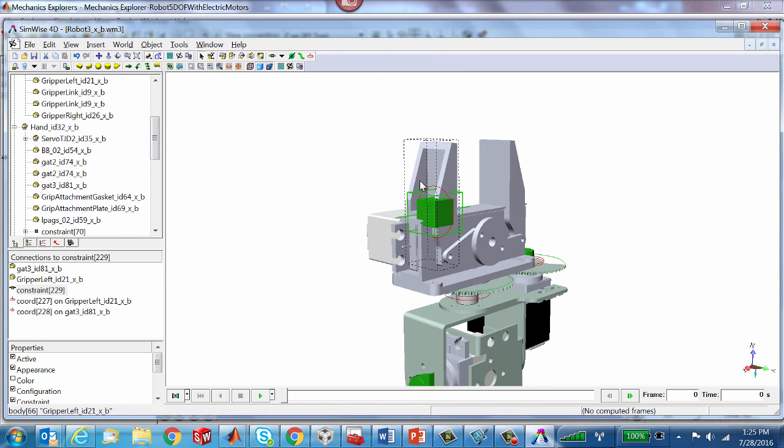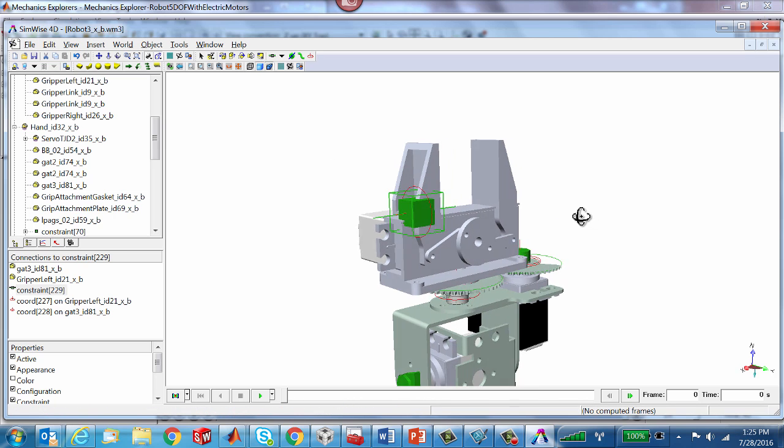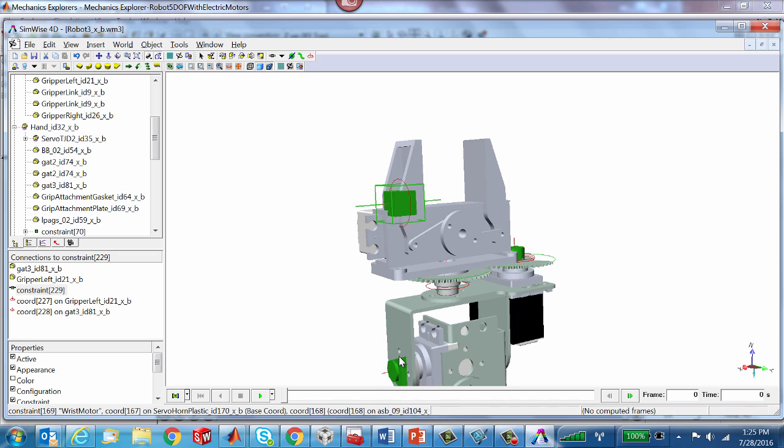Okay, now what it means by rigid is that it cannot rotate, that the two parts cannot rotate relative to each other. What they're able to do is simply slide relative to each other. All right. And the icon kind of represents that. Where Revolute joints are cylinders and Revolute motors contain cylinders that will indicate that rotation axis, these rigid joints cannot do that, right? They can only slide, and you'll see the joint itself reveals the direction it can slide into.